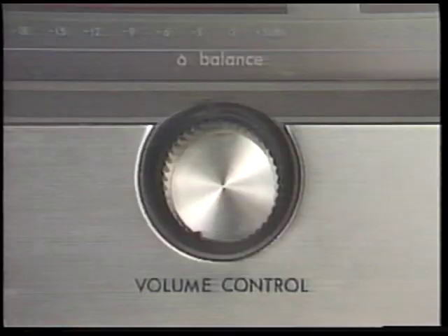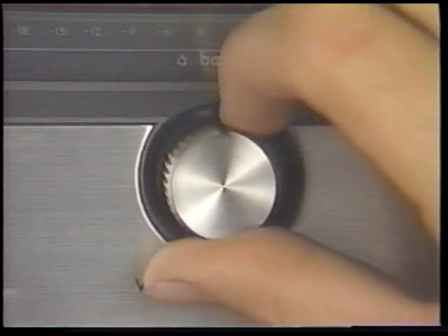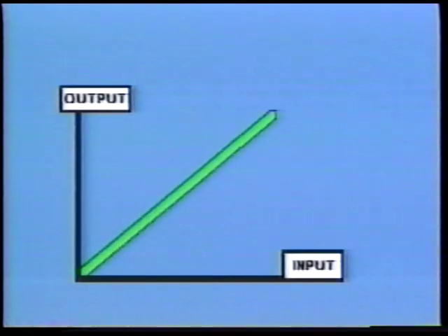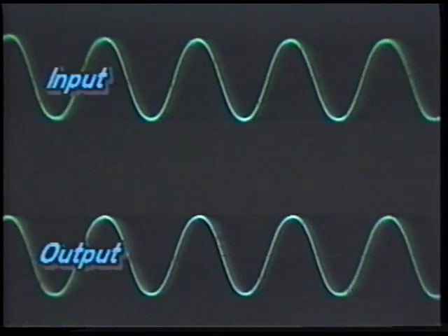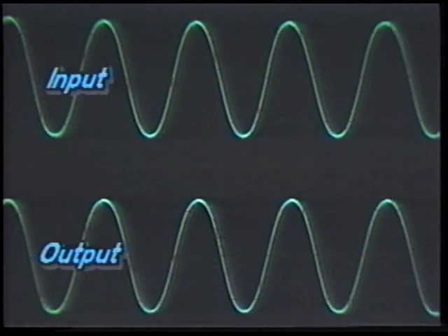Variable gain amplifiers alter the dynamic range of an instrument, voice, or other sound. Returning to visual imagery, it's like controlling the density of a colored light. Most amplifiers are described as having unity gain with a proportionate amount of output for a certain amount of input signal. The ratio between input and output is 1:1, a straight line. You can see that as the input signal rises in amplitude, the output signal increases to the same degree.